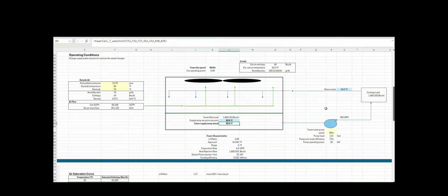Now, if it's a chiller, and let's make this 100%, the colder the water temperature, the better your performance is going to be. Then you're going to want this to be, let's start by saying, as cold as possible. But if you set this to the coldest that it's allowed to have as your set point, you're just going to run this fan speed at 100% all the time and burn fan energy for no reason.